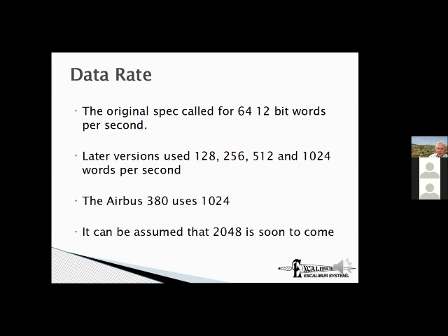Right, because if I've only got 64 12-bit words per second, so a second divided by 64 is a large number relative to the kinds of things we're talking about, and I'll have long bits. Whereas if I want to fit 1,000 words into the same second, then I only get about 10 microseconds per word, which means I get less than a microsecond per bit.